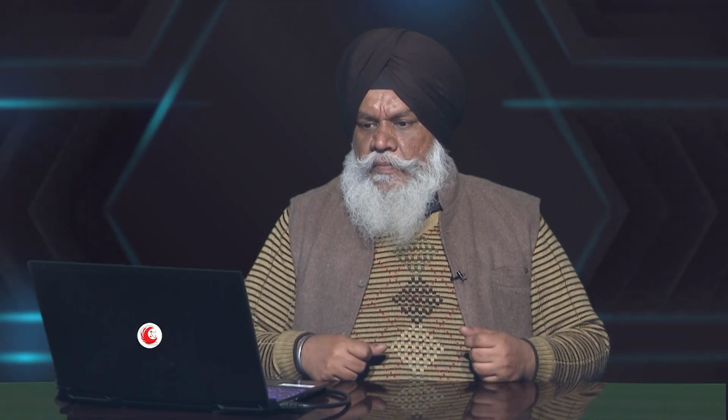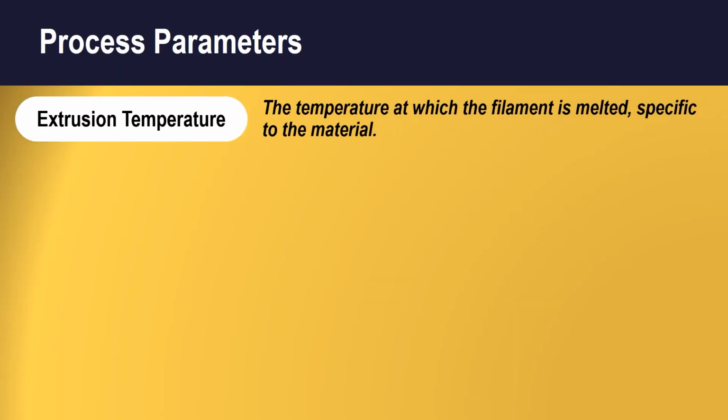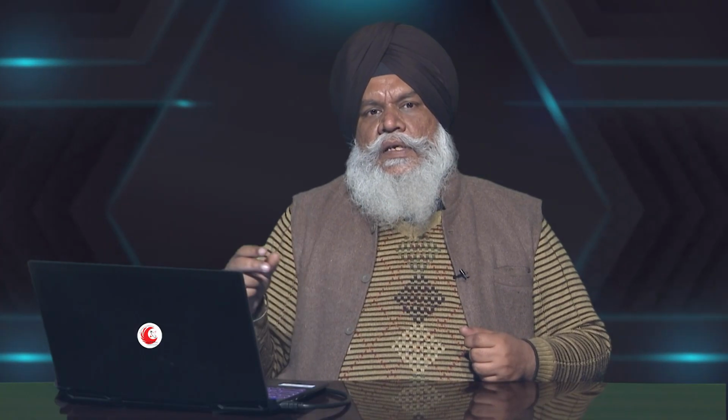Then coming to the process parameters, the most important consideration is given to the extrusion temperature. This is the temperature at which the filament is melted, and this is of course very specific to the material and the application. Like I have already explained in my previous session, let us say I am interested in making some vertebra part. Only PEEK is one of the acceptable materials, that is polyether ether ketone, and the PEEK polymer is processed around 450, right? Whereas if I am interested in, let us say, PLA, which is another biocompatible material, but not for this application, this temperature varies from 150 to 200.